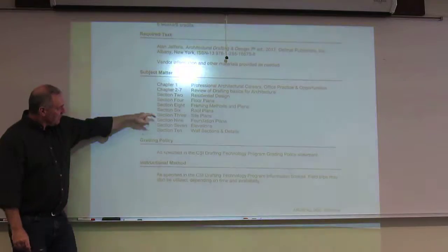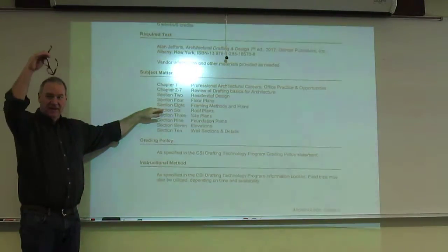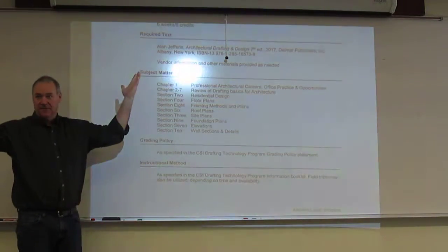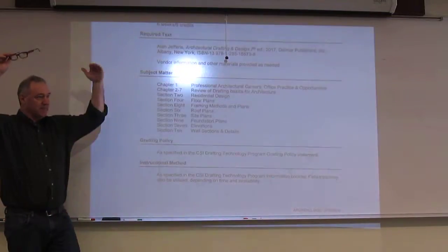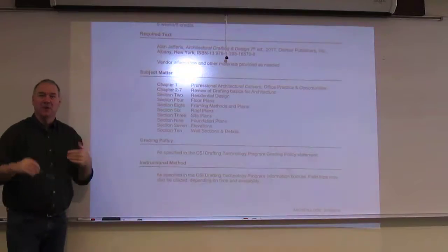After that, when we get our floor plan defined, we generally design from the roof down, okay, because we don't know how big to make the foundation until we know what's sitting on top of it. So you design from top down, you build from bottom up, right? They're kind of reverse processes.